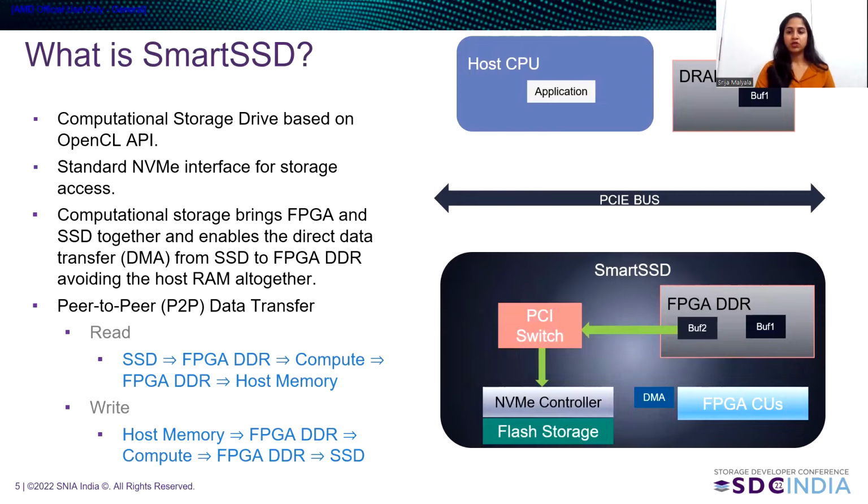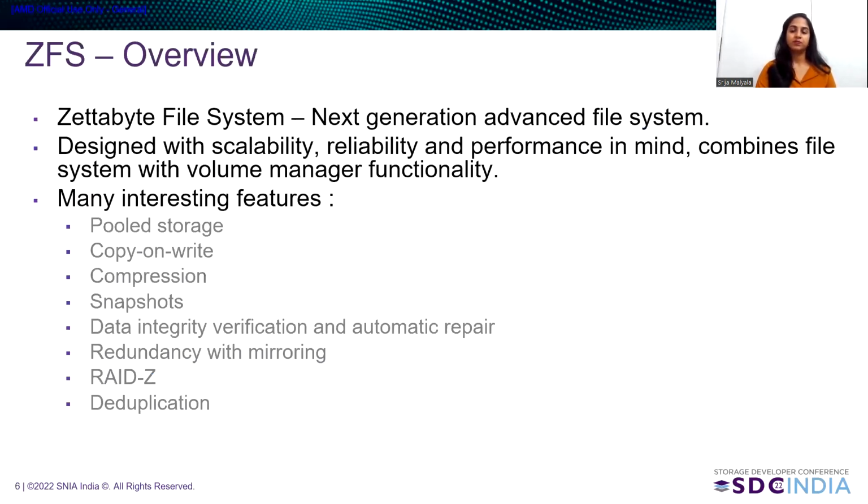This is possible because of the 3-port PCIe switch implemented inside the FPGA, with its ports connected to the host CPU, NVMe SSD, and the FPGA. The entire FPGA DDR is exposed to the host via PCIe bar, allowing the host applications to allocate data buffers from the memory and inline data transfers directly to or from the SSD using the standard NVMe driver stack. So we have offloaded compression from ZFS.